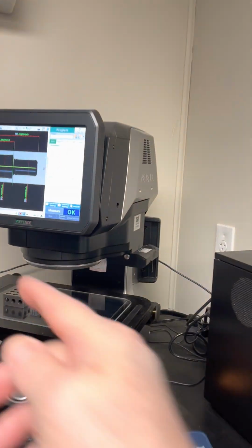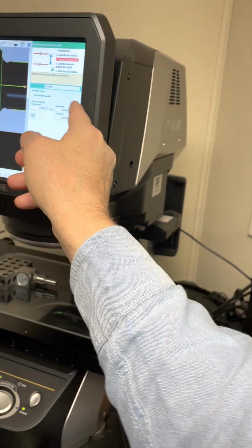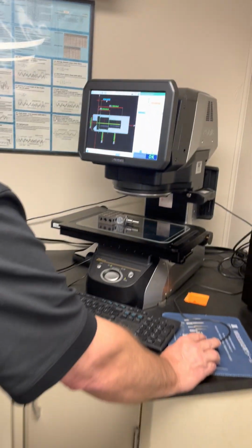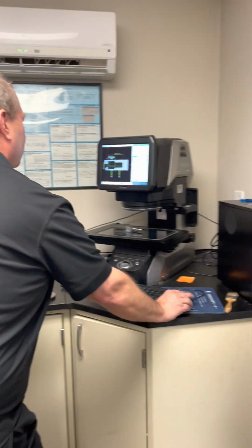Okay. This is the part that gets pressed into a plate, and this is the part that penetrates into the next bushing in the next plate. Gotcha. So we don't want that part, that 875, to be exposed or proud. Okay, so what's the other one?